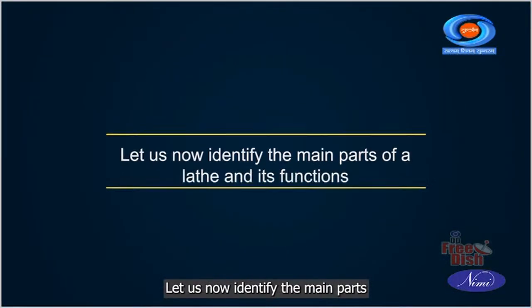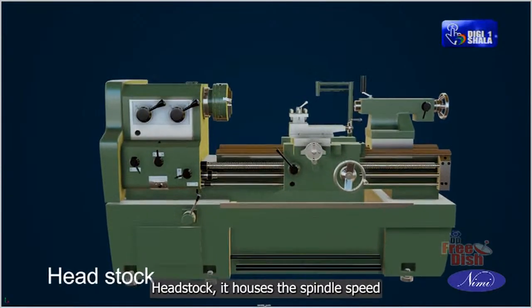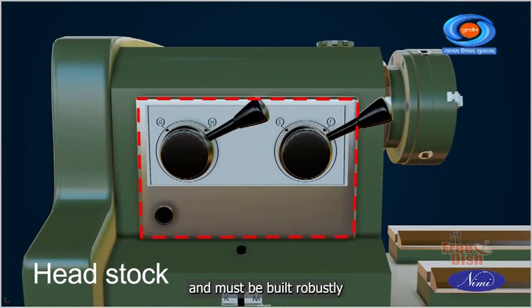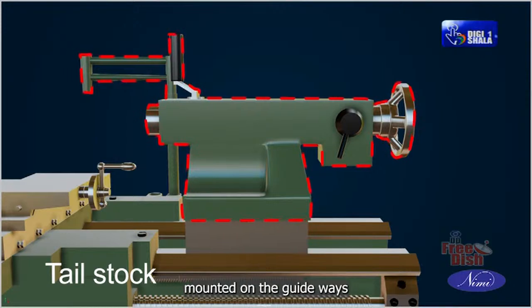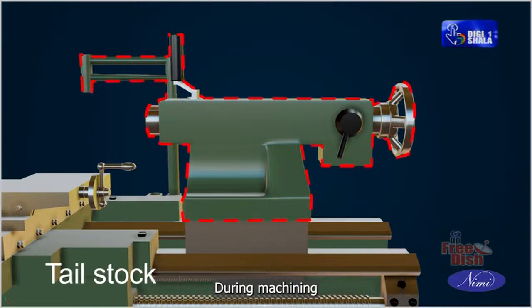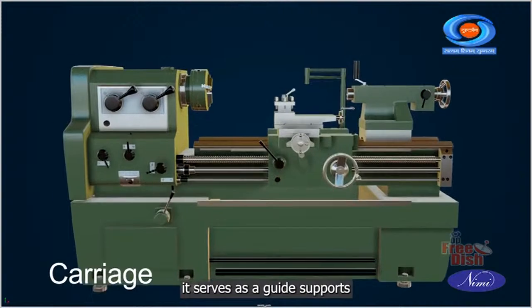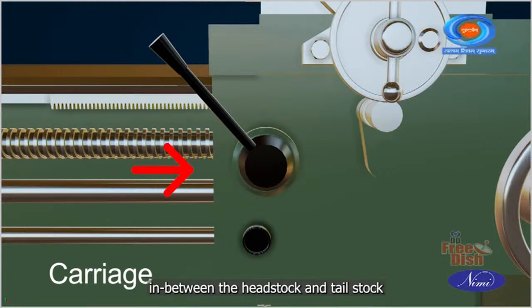Let us now identify the main parts of a lathe and its functions. Headstock. It houses the spindle speed change mechanism and gears and must be built robustly. Tailstock. It is a cast movable part mounted on the guideways of the bed, positioned opposite to the headstock, and supports the workpiece during machining. Carriage. It serves as a guide, supports and feeds the tool against the workpiece and is positioned in between the headstock and tailstock.